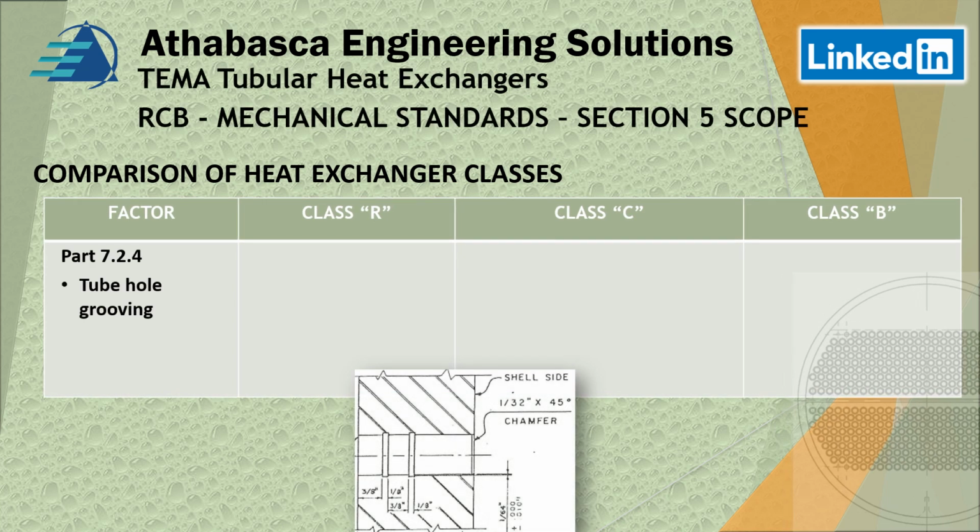7.24, there are requirements for tube hole grooving. And we have an image down there of a typical grooving requirement. So for Class R, if the tube is 5/8 of an inch or greater, then the tube holes must be machined with annular grooves.